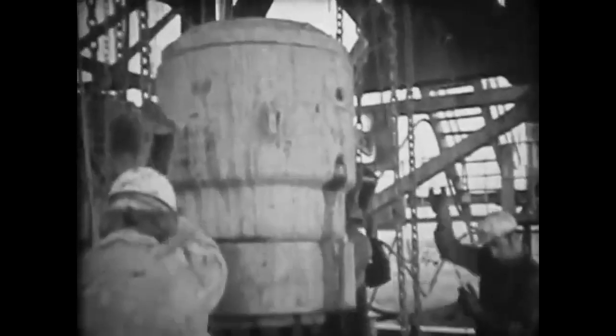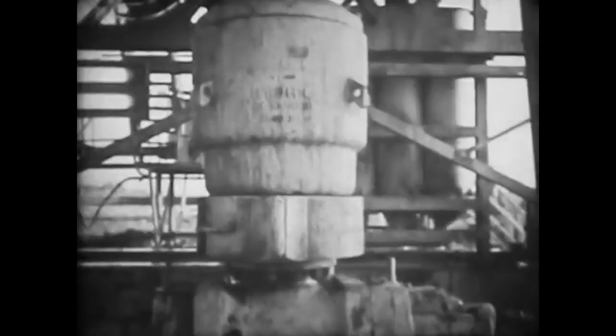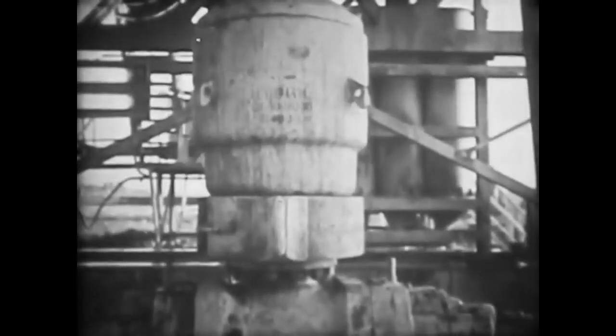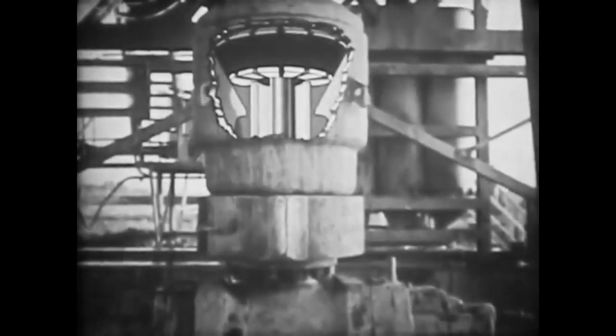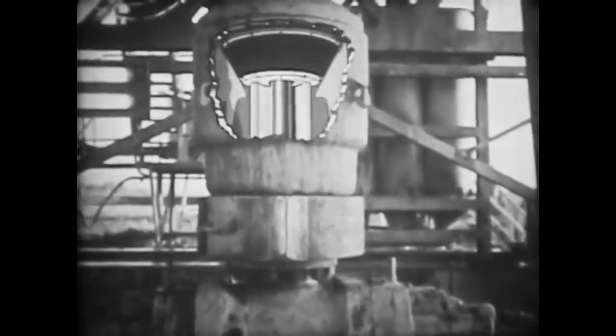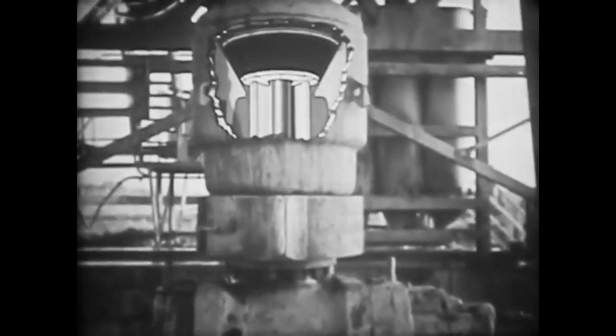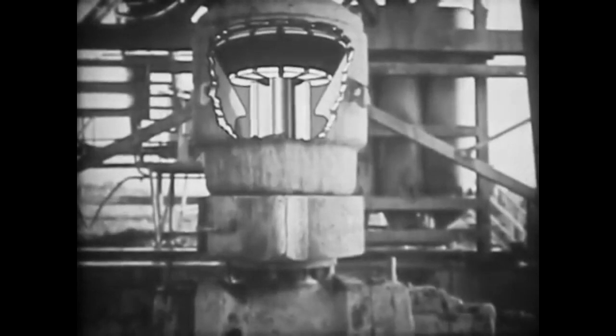Now we can cap the top of the casing with a set of safety valves, known for obvious reasons as the blowout preventers. If further drilling were to encounter extremely high pressure gas, oil, or water, we could have a problem. To contain it, we need a means of sealing off the hole at the surface. It's done by hydraulic rams that close off the gap between the drill string and the inside walls of the casing.